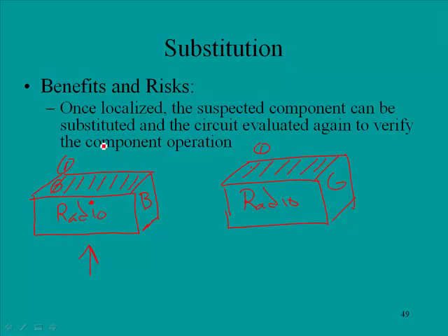Now, just for sake of discussion, we'll pretend that he determines that circuit card number 4 was the faulty component, and so he would probably go over to his supply system and order circuit card number 4. He would put it into the radio, and the radio is fixed. And this is the concept of troubleshooting by the method of substitution when you have a group of known good components.